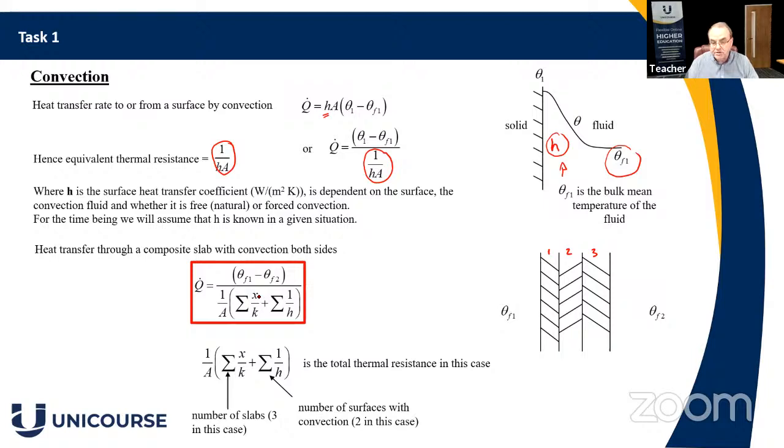So we've got 2 components in the thermal resistance now. If we look at the thermal resistance, this is the thermal resistance at the bottom for this system shown on the right. So Q is through that system. We have convection at the inner surface, and we have convection at the outer surface, and we have conduction, conduction, and conduction through the solid material.